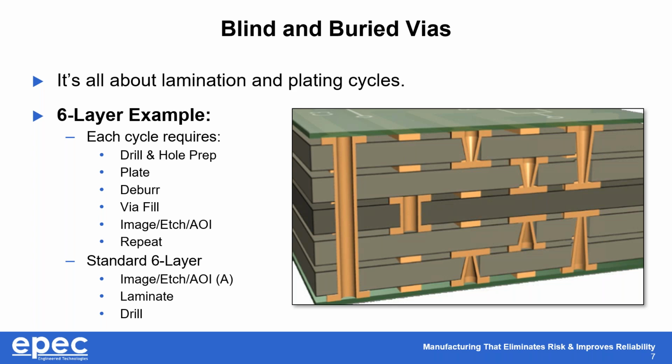However, one of the things that we need to understand as a fabricator is if we can start looking at this well before you send us an order, we're going to have a lot more effective ways to put strategies in place and maybe give you some suggestions to keep you from potentially making a decision that's going to add lead time to it. And there are things like blind vias and micro vias and putting them on different layers that give us a fighting chance, right?